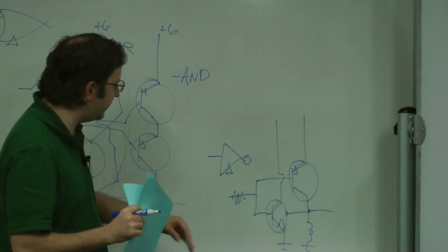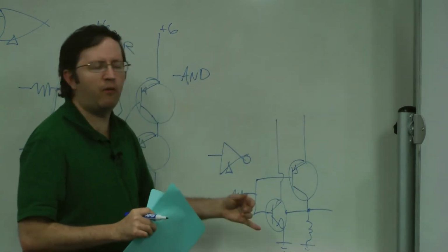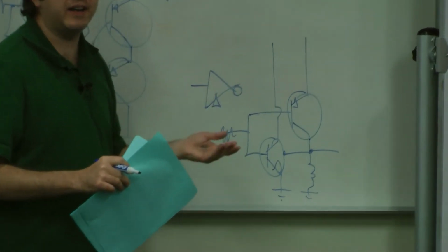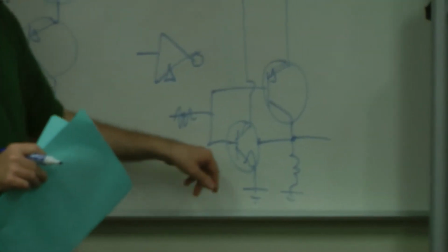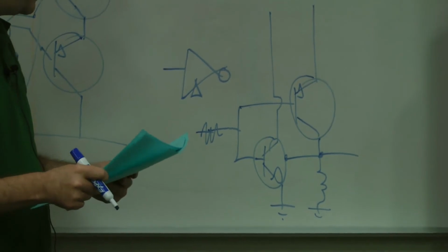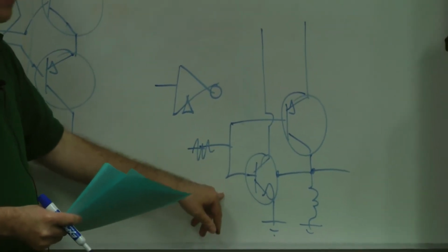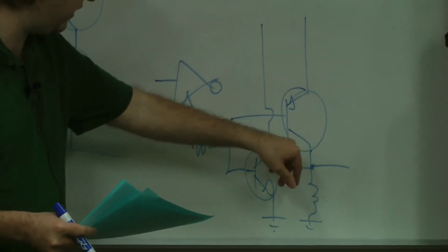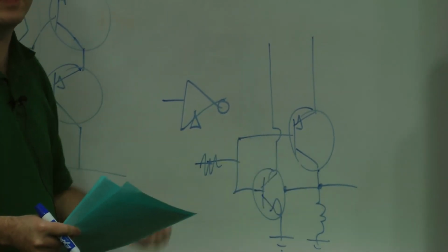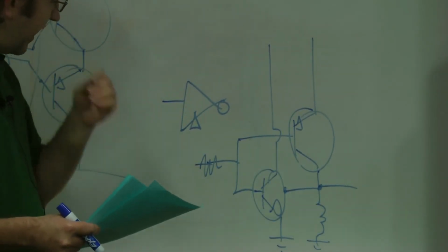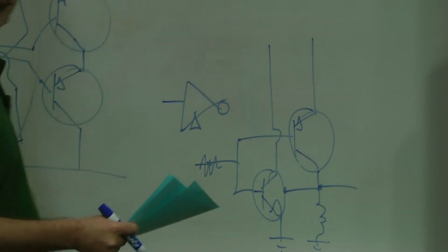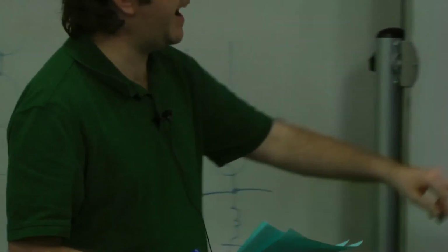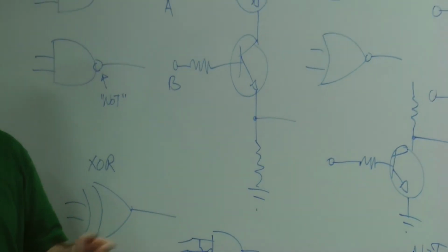Whenever I tried doing this particular circuit, one transistor or the other would end up getting too hot, and this is a circuit where I released the magic smoke. I'm not entirely sure exactly what I'm doing wrong. I do know that if I created either of these two gates separately, it would work as expected, and I think I even confirmed that I could do a ternary AND gate and have that work as expected.